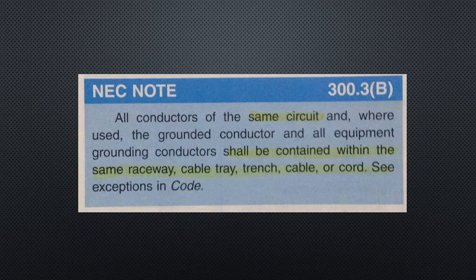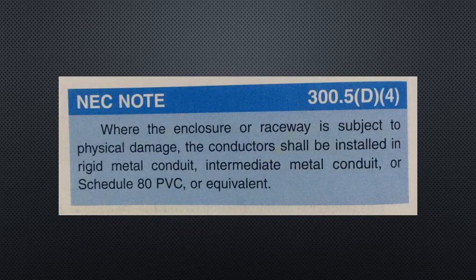If cables or non-metallic raceway is run perpendicular to exposed studs, rafters, or joists and subject to damage, strips of 1x1 or 1x2 wood stock should be placed along either side to protect the wiring from damage. For this, see figure 5-2.